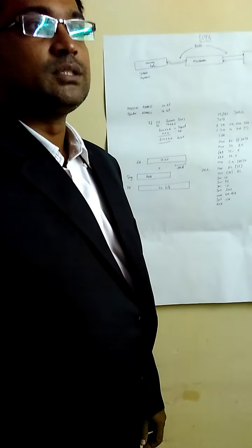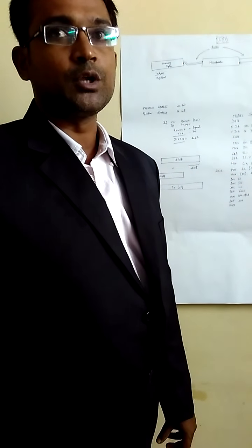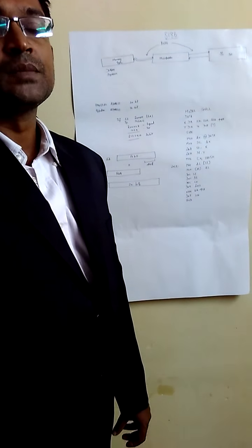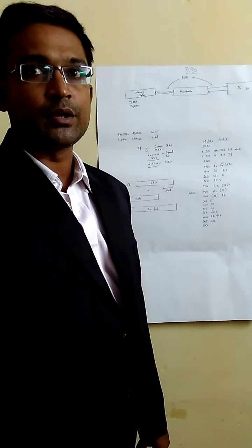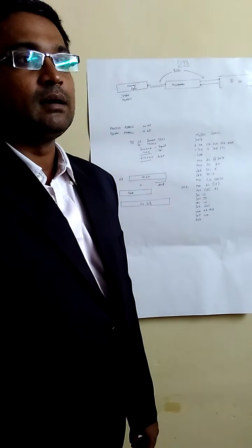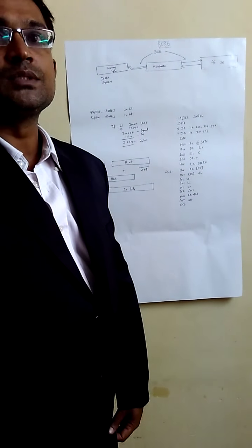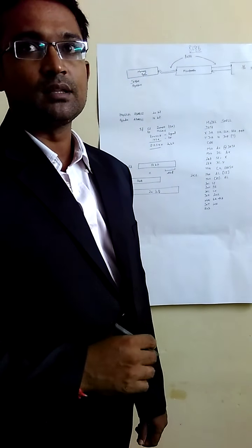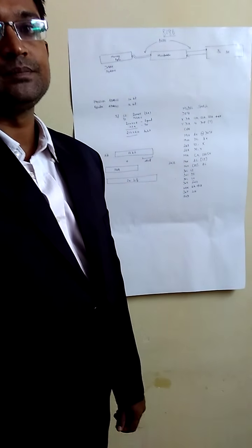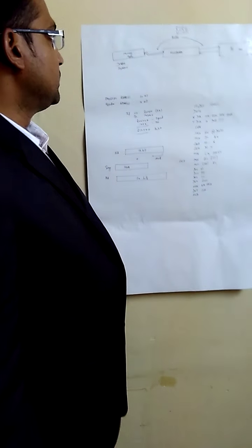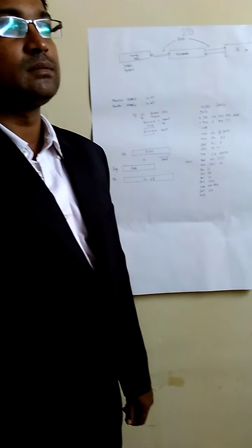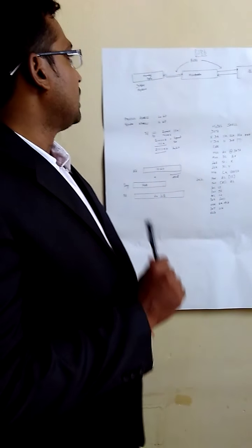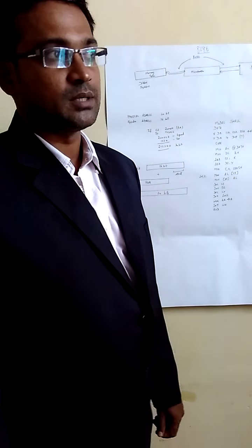Now in this session we are going to see the block diagram of the microprocessor and how the address can be calculated for the 8086 microprocessor, since it is coming under the CISC microprocessor family, and a sample program which performs movement of a block of data bytes, that is 8-bit, from one place to another place without overlap. The block diagram involves a microprocessor and its architecture, and is connected in between the memory subsystem and IO subsystem.